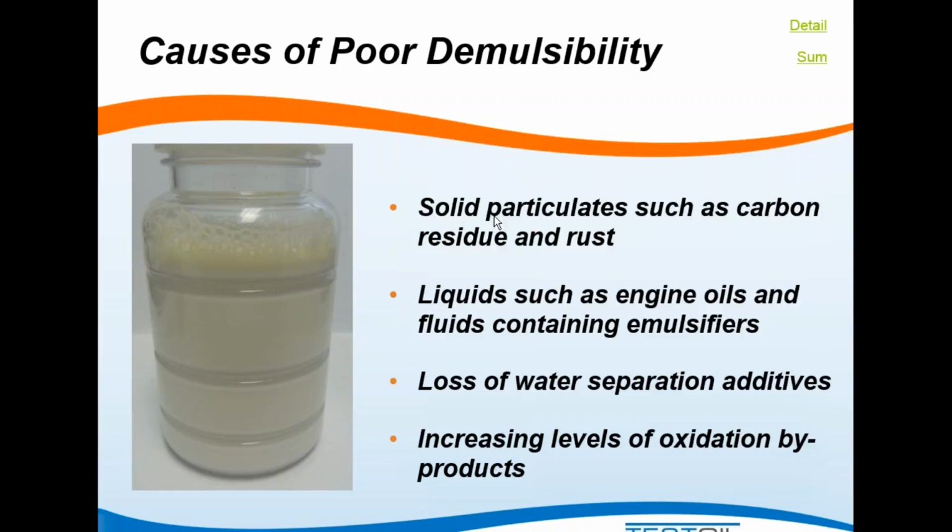However, keep in mind, this is just a failing result if you get water in. If you have a system where there's no potential for water contamination, you may just want to take that under advisement. Just consider, well, this oil doesn't really separate from water. However, the chances of water contamination are very low, and keep an eye on the other test results, but maybe this oil will be sufficient for continued service.